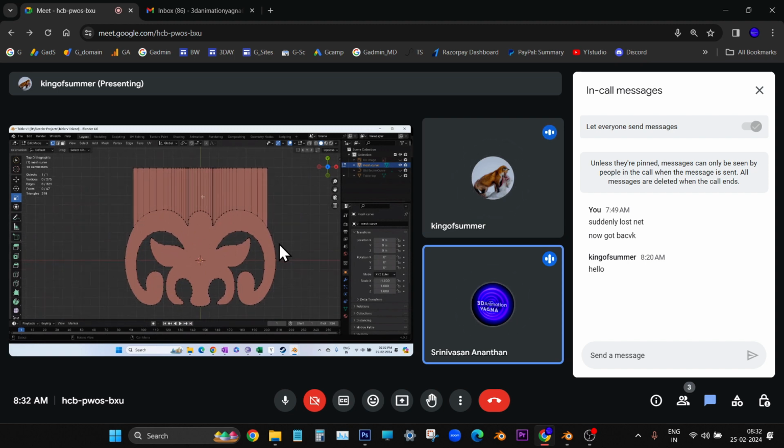Now, from the top right side corner, that vertex you have to select. Start from that vertex. No, in the geometry I'm saying. The geometry come to view. So again, go back to the circular select. Press W on the keyboard. Just by pressing W, you'll go there. Now start selecting.